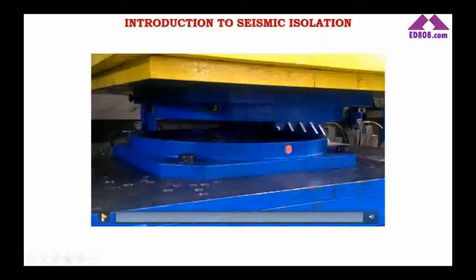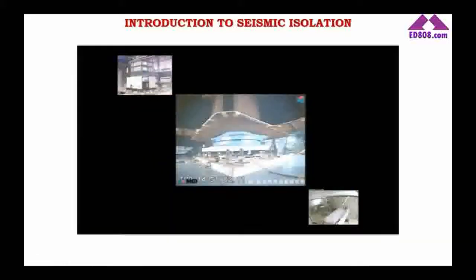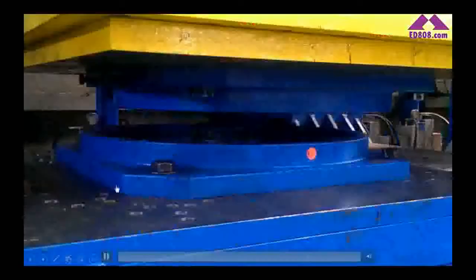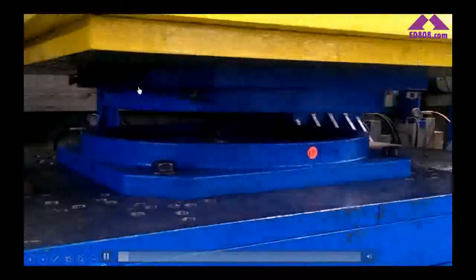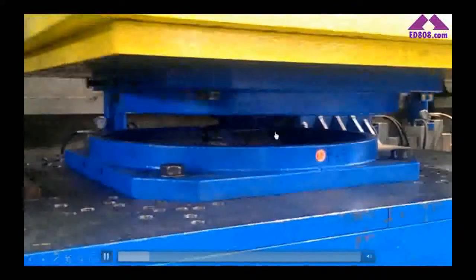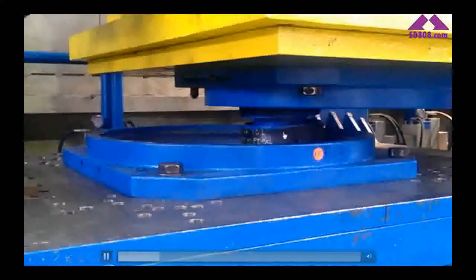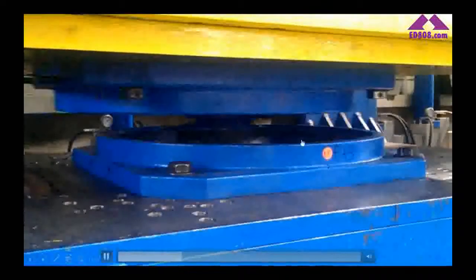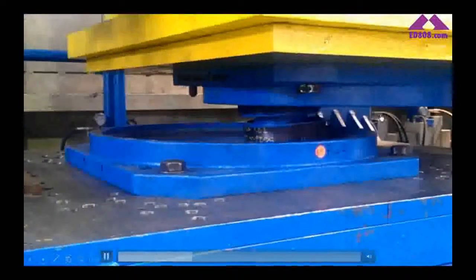Here is a test video that I recorded during one of the tests of triple friction pendulum. You will see how the inner part moves and also how the isolator moves. Notice that the first movement starts at the inner part. Then it moves at the outer concave surface.